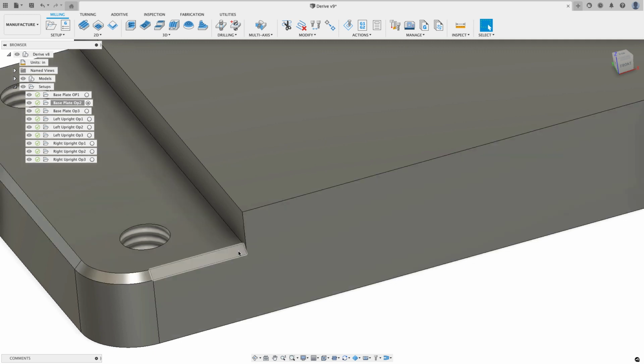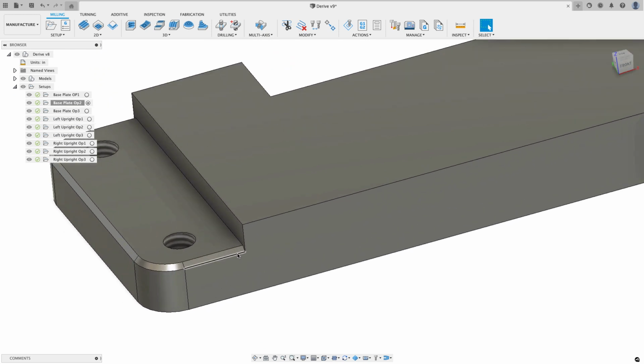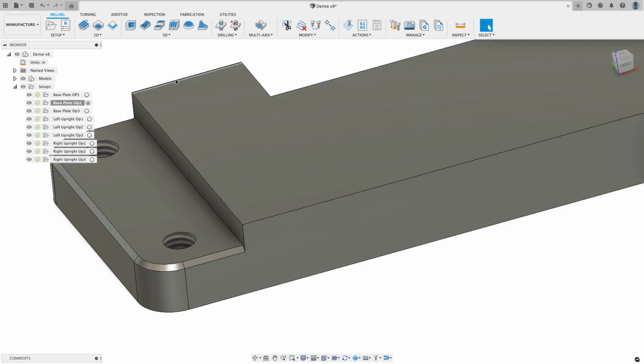This chamfer is easier to program in the CNC environment if the chamfer doesn't exist. I can use the 2D chamfer command. Whereas if this chamfer is on the model, I have to use 2D contour and figure out how to back the toolpath off so it doesn't run into the vertical wall. If that chamfer wasn't there, I could use the 2D chamfer command, and the software would automatically figure out how to stop that tool short of hitting that vertical wall. So as a CNC programmer, I'd like to take that chamfer off.